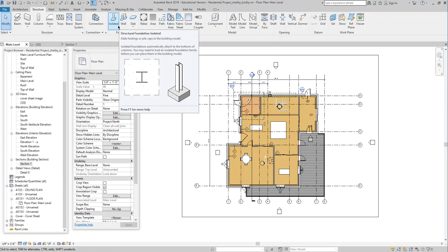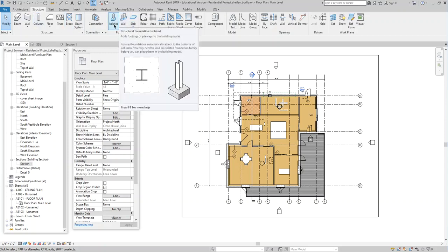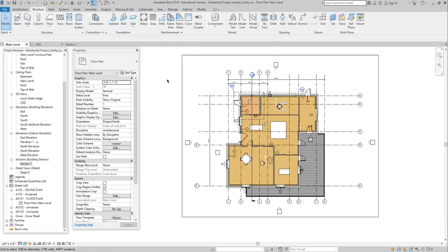So somebody who went into your model would assume that they're not from the design team, right? They're from the structural engineer. So we try and stay away from items like that, right? We don't want to use the defined foundation wall or the defined footing tool in the Structure tab. Okay, we're going to stay away from that. They're actually pretty easy to generate, but they're really difficult to redefine. So all things aside, we're just going to stay away from these two tools.